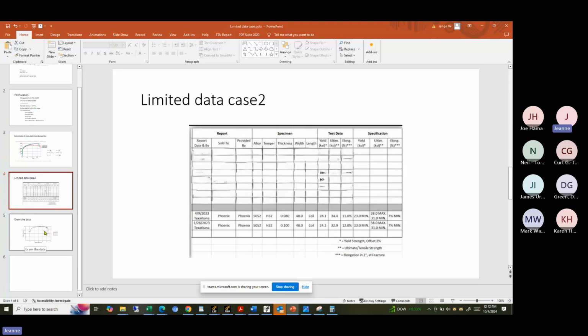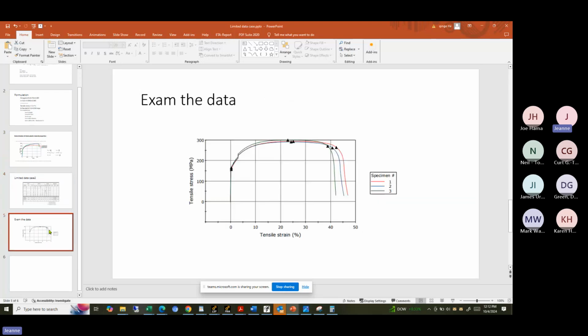One more thing I'd like to talk about is to always examine the test data. If you send your material to a test lab, you always check the curve. This is garbage. If you look at this curve, it goes up and jumps like that. First, I don't like this slope. The beginning slope is not this smooth, normally it's sharper. We traced it down and had the customer talk to the lab. They said they changed the speed right here, because they try to save time. If you compare two materials, you can do that, since both materials change speed and jump there. But for us, this messes up everything. If you have this, send it back to the lab, have them redo it, and tell them you cannot accept this.